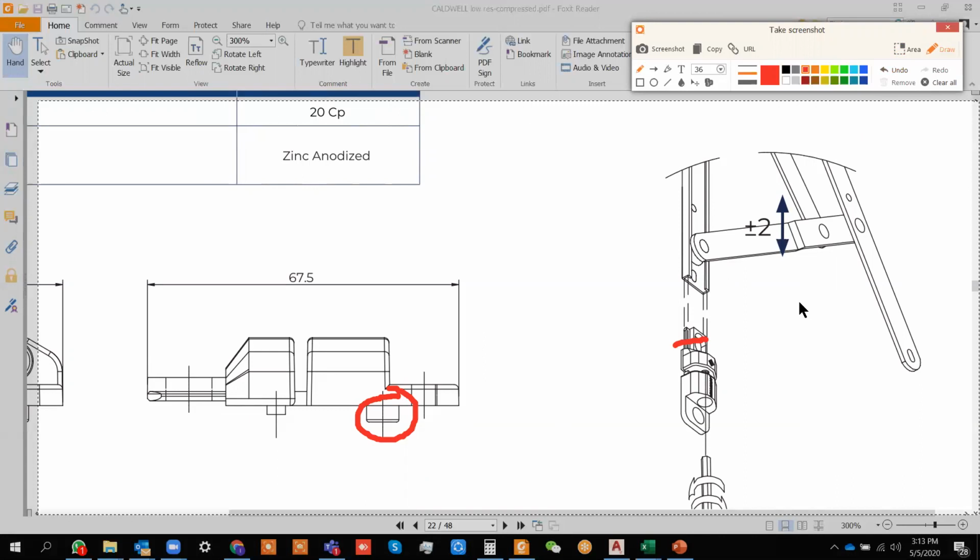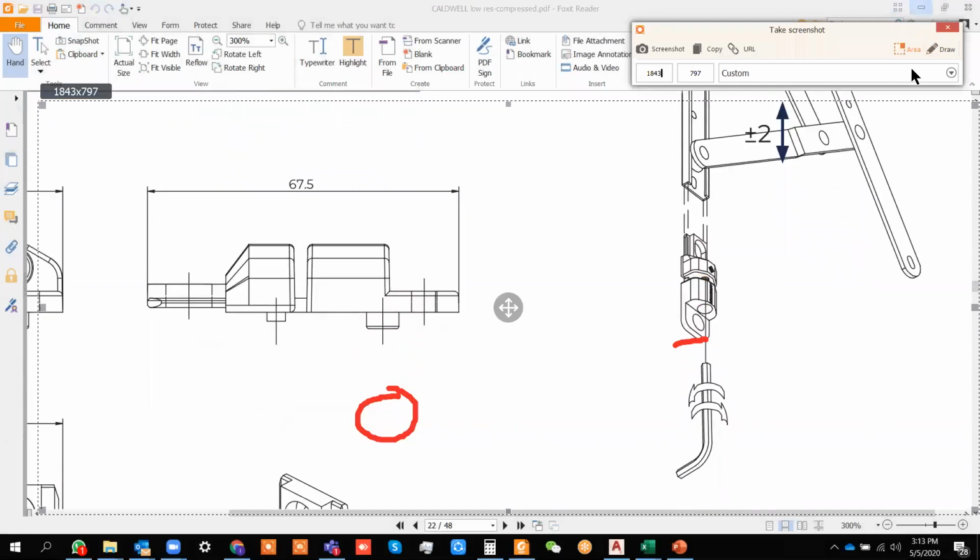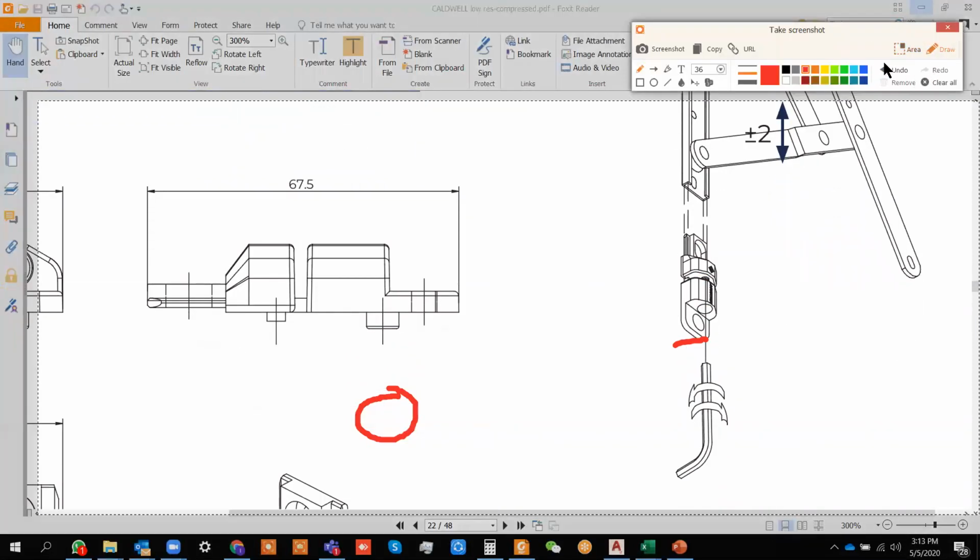But if you feel that the window is not in the correct position, and it needs to be lifted 2 mm or taken down 2 mm, then it's very easy with the help of this device. You can just tighten or loosen with the help of an Allen key and take the whole window up or down by 2 mm.